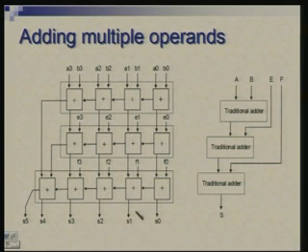The signals have to propagate horizontally. There is a carry rippling through, and there is propagation vertical also. You are going from one stage to other stage. So, the last thing which will get computed is the MSB of the final result. It has to account for propagation in this direction as well as in that direction.